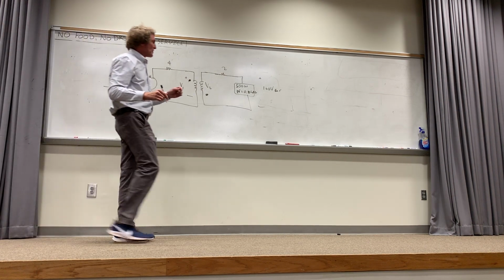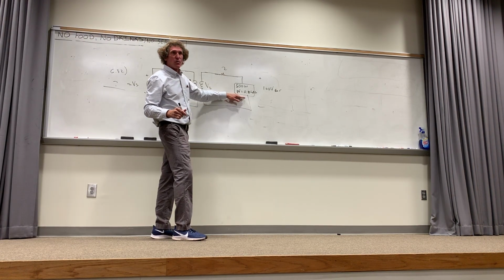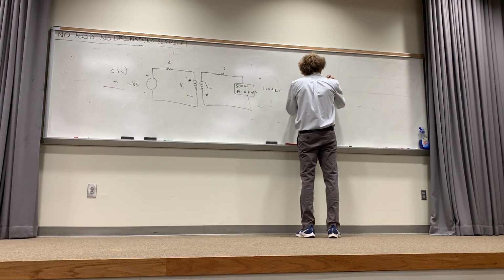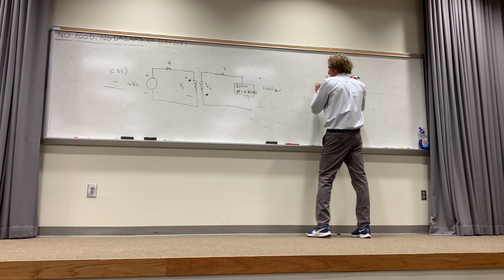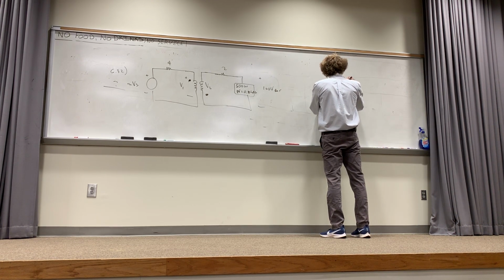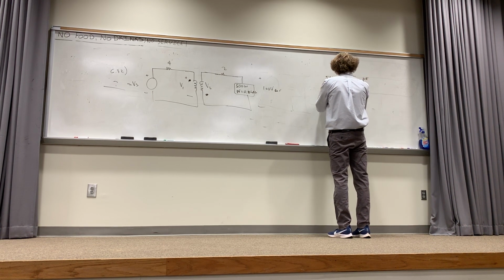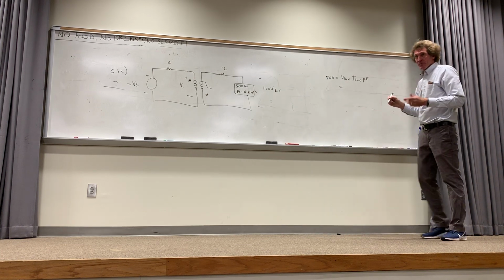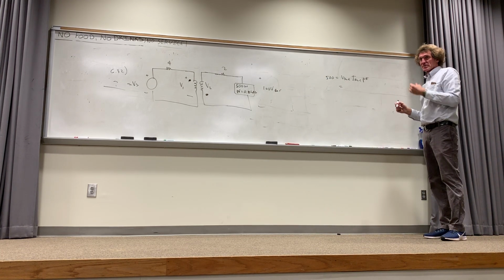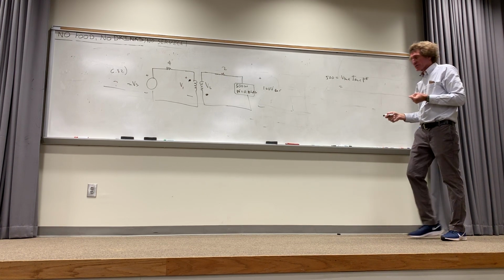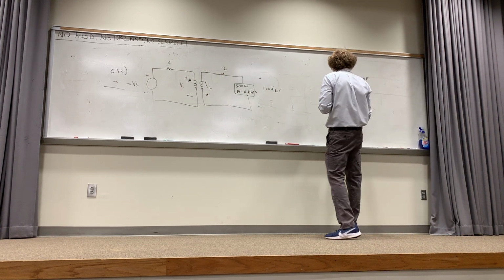All right, now when I come here right away, if I have 500 watts, it does say 500 if you look at the problems, right? That means 500 watts is equal to VRMS times IRMS, these are magnitudes, times the power factor. Right? V I power factor is equal to wattage, correct, class? It's the projection of the complex power on the horizontal axis. It's real power. So to get IRMS,